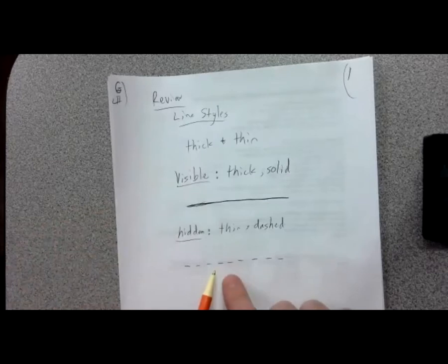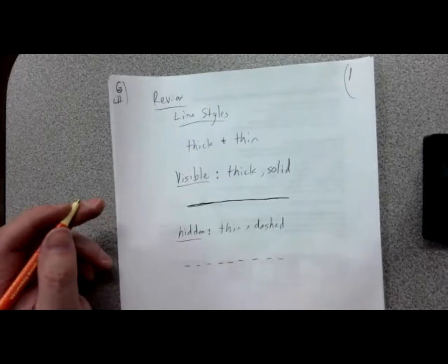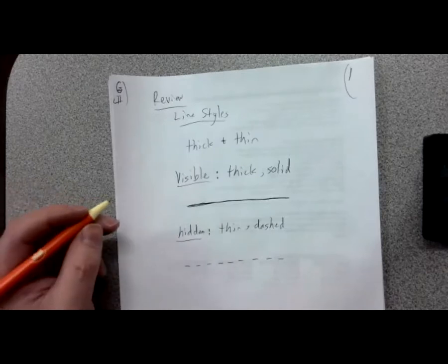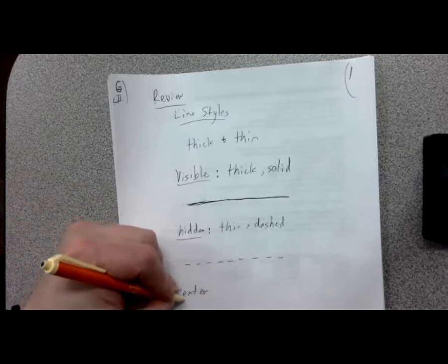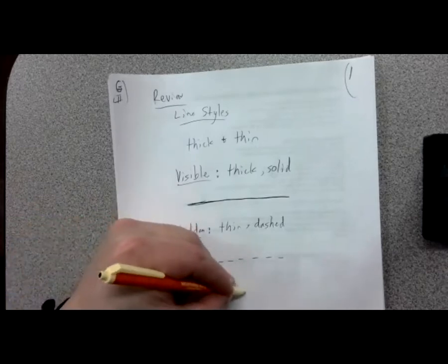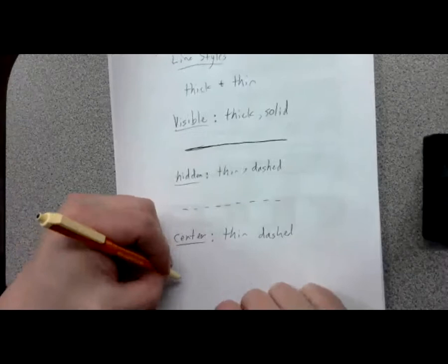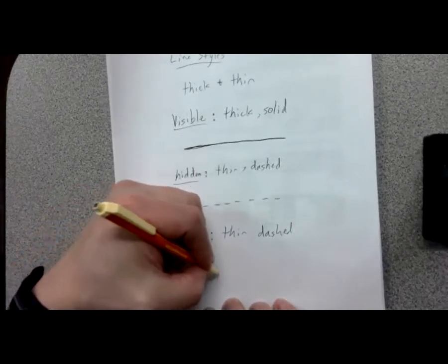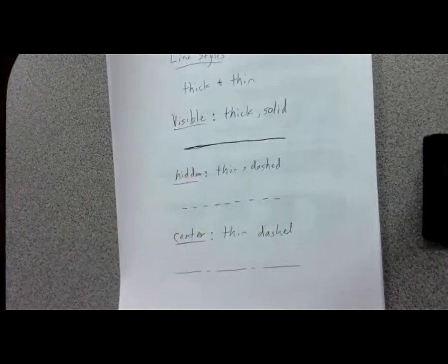We talked in the video and also in the text I've made available to you, there's information about the size of these dashes. I'm not going to measure your dashes when you're drawing them by hand, right? Just, it's a short dash repeating. Thin line, short dash repeating. And from time to time, we will see the center line. That is also a thin dashed line, but the pattern and size of the dashes is different than the hidden. So again, thin line, so pen or pencil, I do my best to just make a single pass. The center line is a long dash, short dash, long dash. Okay.